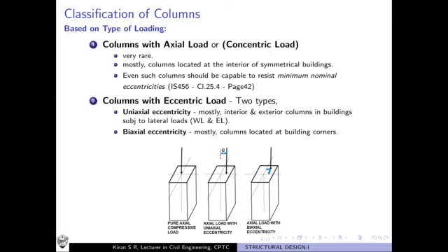One more thing to be kept in mind is that even if it is a truly axial load and we can design such columns for these axial loads, the Indian Standard Code says that even such columns should be capable of resisting minimum nominal eccentricities in loads. Due to unexpected events, moments might develop in such columns also.